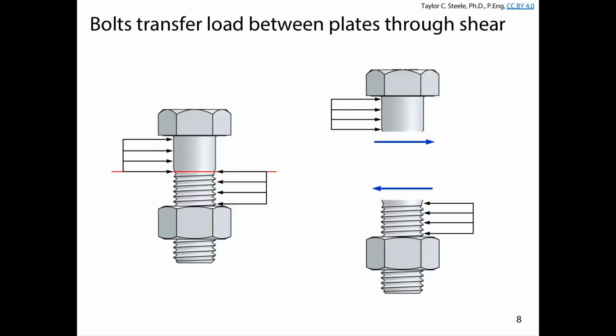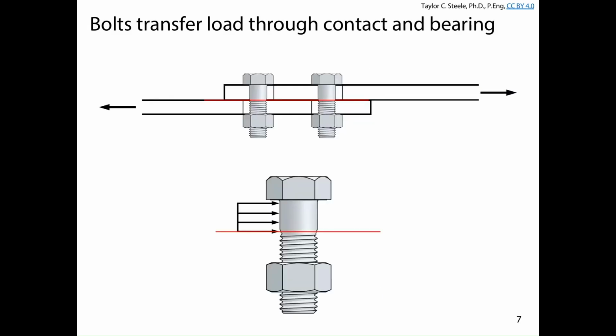How this tends to work is that there's a bearing stress that develops. Oops, I guess I should go back here. Yeah, there we go. So, yes, I got ahead of the horse a little bit here. When you first install the bolts, the tension members tend to, well, they're not in complete contact, but as we apply tension force, those tension members start to slip relative to the bolts. We develop some bearing on the bolt, so there's some bearing stress that develops on the left-hand side, some bearing stress that develops on the right-hand side, and it's ultimately the equilibrium that develops through that plane.